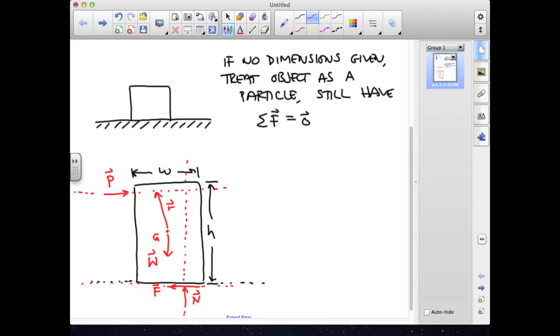Each of these forces will tend to impart a rotation about G in addition to a translation, and the extent to which they tend to impart rotation will depend on both the magnitude of the force and the magnitude of the eccentricity. If the piece of furniture is an ottoman, it is short and squat with width much greater than height, and you probably don't have to worry about overturning it as you wrestle it around the room. If it's a chest of drawers or bookcase with the height larger than the width, then you have to be careful moving it in that you don't tip it over.